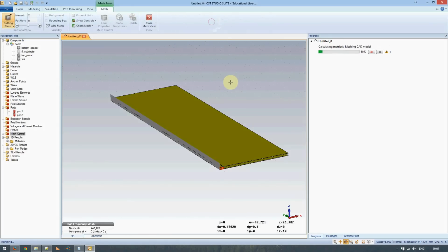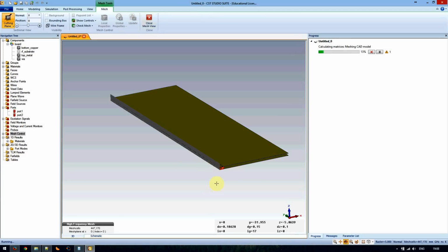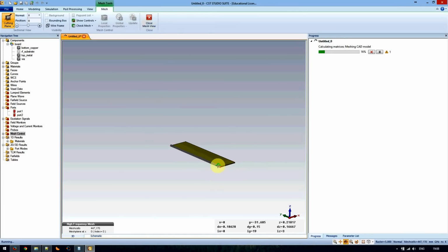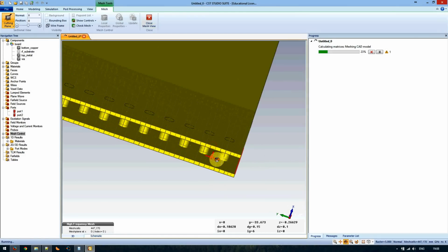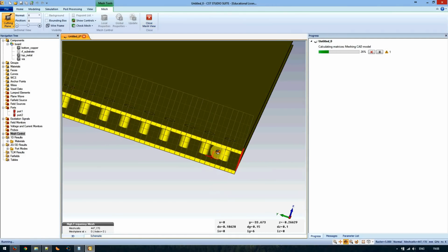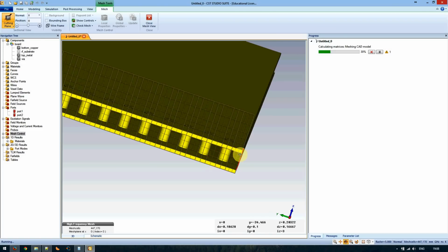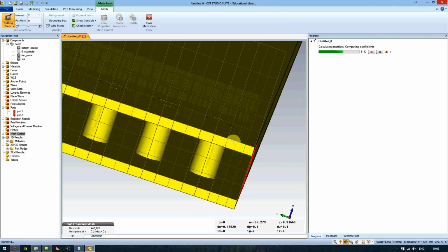So what you may like to do is click on mesh view, and that will show you how it is discretizing the model for simulation. Now, an interesting thing about the time domain simulator, or solver rather, is that the first 3 mesh shells after the port need to be homogeneous. Luckily, because we are at such high frequencies, the mesh that it's generated has 3 first homogeneous cells, although you may notice that these are a little bit thinner than the ones over here.